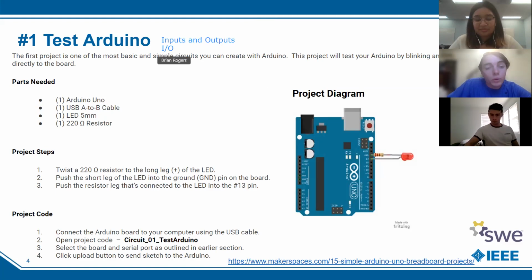What we're going to be doing here today is, you'll see in our little Arduino here, we're going to have an LED and also a resistor. We're going to hook that up to create the most simple circuit you'll see in electrical engineering. What else needs to happen is we need a source of power, because in order to make an LED light up, there has to be some source giving power to that LED. And then we also have to connect it to ground, because that power has to finally reach an endpoint.